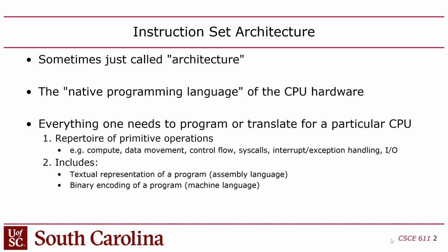And so basically there are three main things that an instruction can do. Number crunching, compute, like add, subtract, multiply, divide. Or load and store, which is to interact with the external memory. Or control instructions, meaning to branch or jump somewhere else to implement a control construct like an if statement or a loop. Those are the three main. Now there are other instructions, like interrupt handling, syscalls, and IO, but generally speaking, when you write assembly code, each instruction is really just doing one of those three main things: compute, load/store, or branch/jump/control.